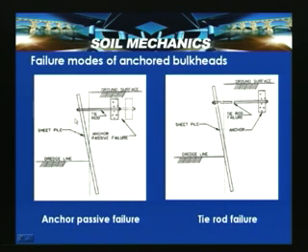So, there will be excessive movement at this point. In fact, when the anchor bulkhead is there, the moment at this point is 0 and the deflection at this point should be as minimum as possible. Similarly, suppose there is a case where a tie rod has been kept which has inadequate load capacity. In such a situation, a breakage failure or rupture failure of the tie rod can occur.